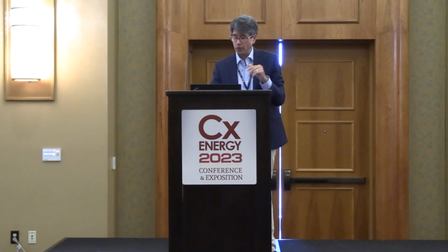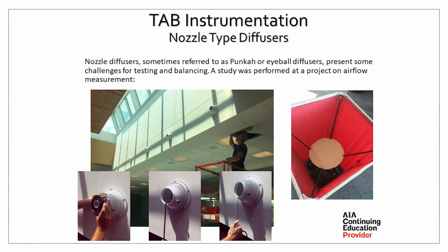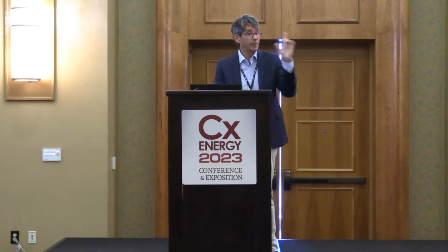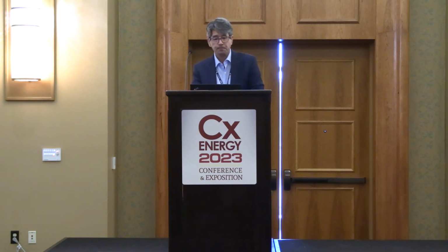We used the flow hood 2 ways. One, we call it a blast plate. Luckily, the manufacturer now is making some things in this neighborhood, but it's a piece of cardboard in there. If you imagine, the reason that was put in there is that the jet airflow hits it and disperses, so we have a more even airflow going across the flow grid now. And we did it without the blast plate.